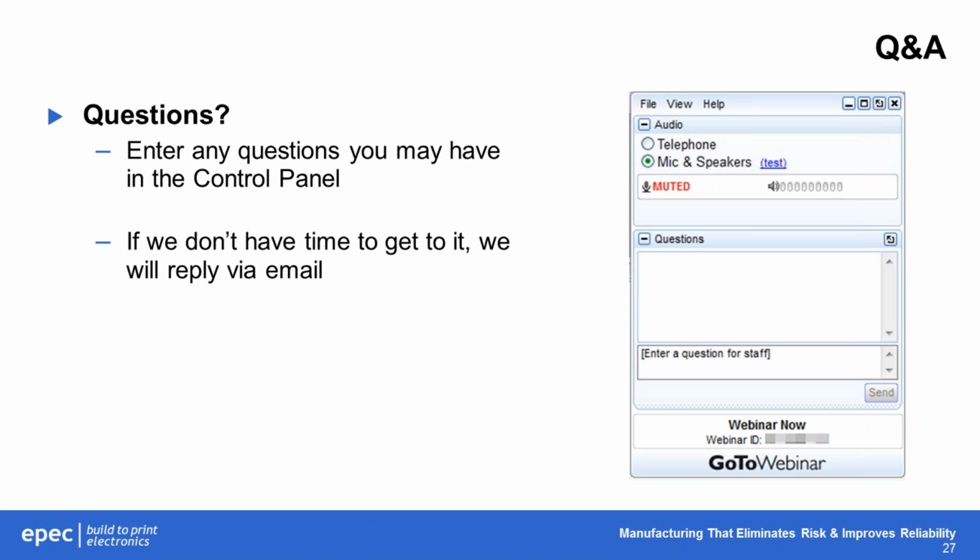Bookbind rigid flex constructions are getting fewer and farther between from our perspective. They're very expensive constructions to manufacture. There are some potential solutions to avoid it. We see the demand for bookbind and also the supply chain for bookbind diminishing somewhat year over year. But they are available, but they are extraordinarily expensive constructions to manufacture.